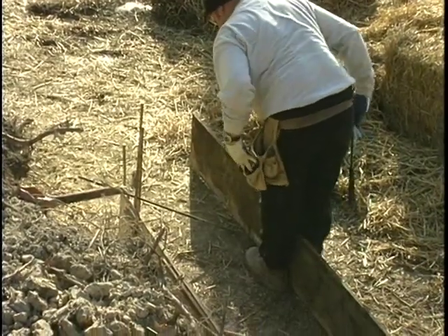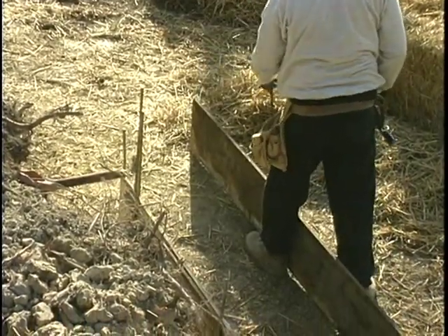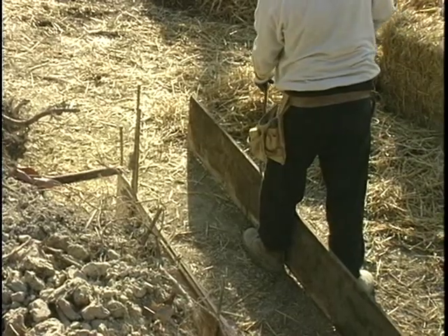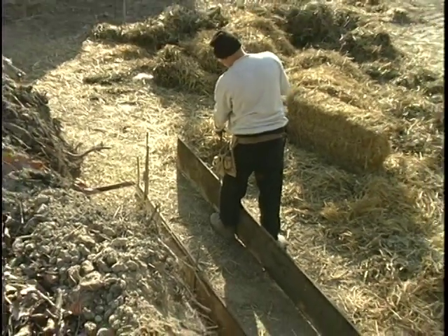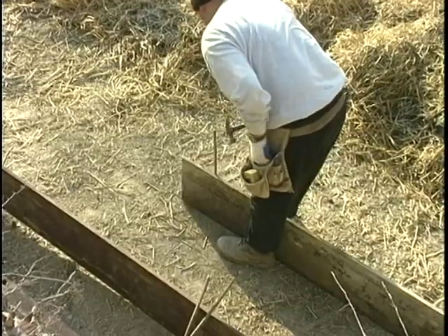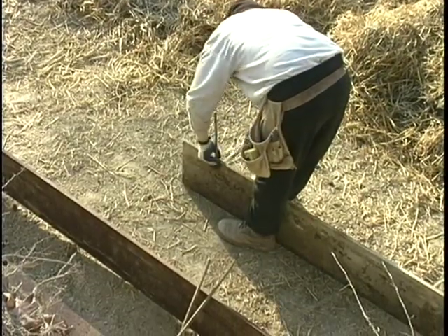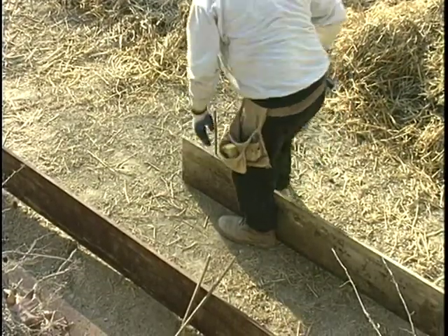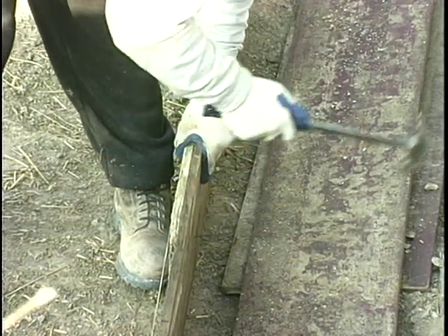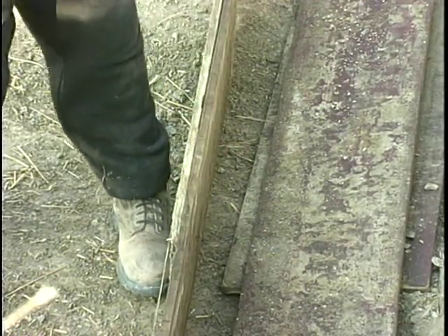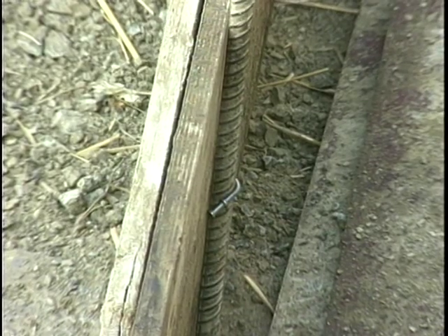Use a tape measure to establish the width of the footing. Then, install the adjacent form boards at the correct distance from the outer form. Nail the forms together using duplex or double-headed nails. This will allow you to easily remove the nails and tear down the forms after the pour.